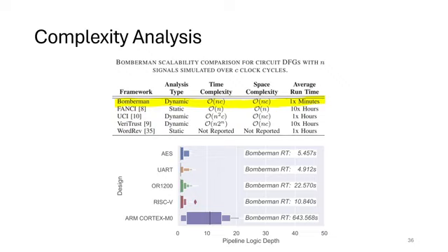The classification of suspicious state-saving components by far dominates the identification stage, and so it defines this time and space complexity. NC basically means there's a data flow graph that has to be traversed with n nodes, and there are C simulation clock cycles. So it's n times C. That's the time and space complexity.